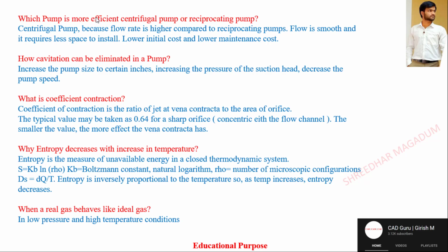Considering the pumps, which pump is more efficient, centrifugal or reciprocating? They will ask that. The answer is the centrifugal pump, because the flow rate inside it is higher than in reciprocating pumps. The flow is smoother, it requires less space to install, and it has lower investment and maintenance cost.